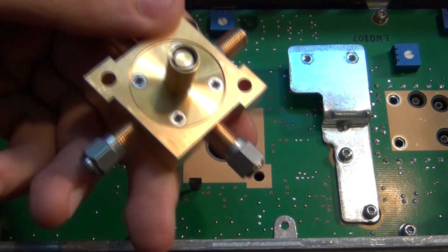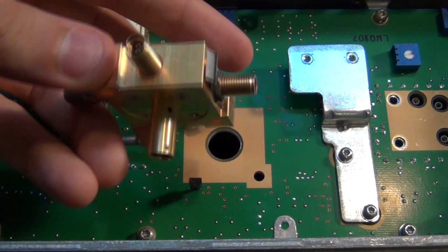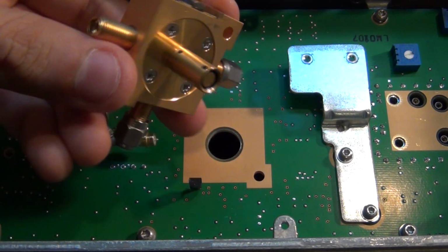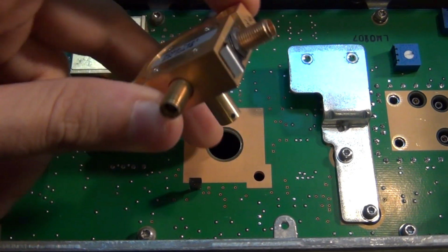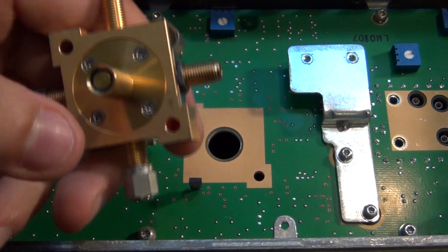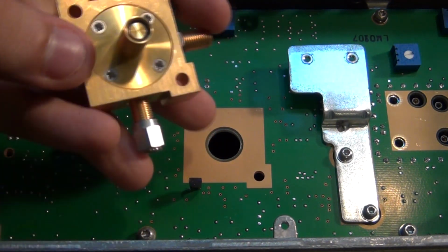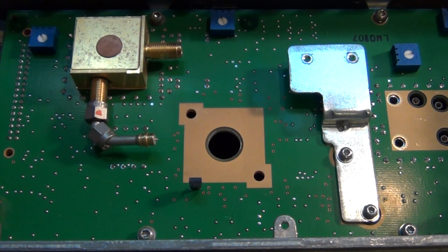The reason is because this is a really high power component, and if you look at it, you can see it has absolutely no DC biasing at all. So the signal coming into it has to have a tremendous amplitude. And by monitoring the temperature, they can adjust the input level required in order to get the optimum response out of it. That's why they need to know what the temperature of this is in order for it to work well.